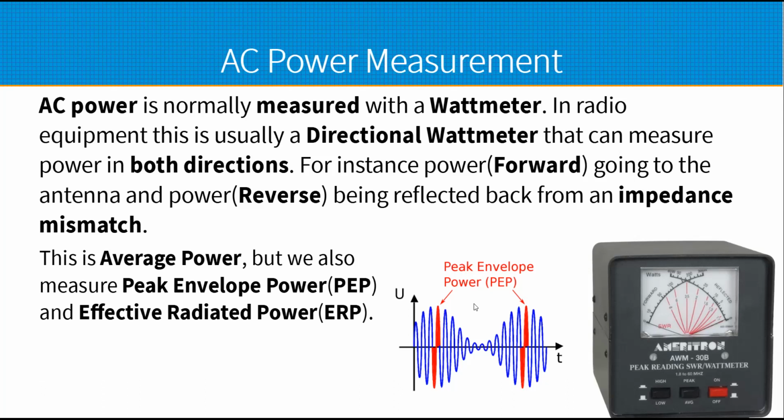I mean, the same power, you don't actually gain anything. You just redirect it like a flashlight. Forward, the reflector reflects the beam forward. Well, if you didn't have the reflector there, the same power is coming out of the light. It's just you're concentrating the beam. And that's the way beam antennas work.